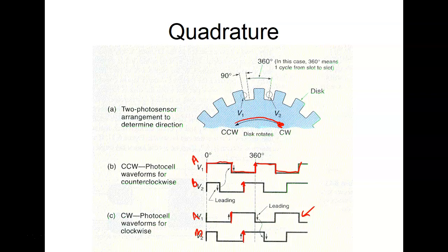So this is what the robots have on them right here. If I've got something that runs in one direction, I don't need one of these. I could use just a standard incremental encoder. Otherwise I've got to have a circuit that handles the direction. By the way, most of your programmable logic controllers now use two inputs, and it does all the math for you. Most of your new PLCs have inputs that handle these quadrature encoders directly. So you don't have to really do anything. It'll give you the direction, the count, and the speed.